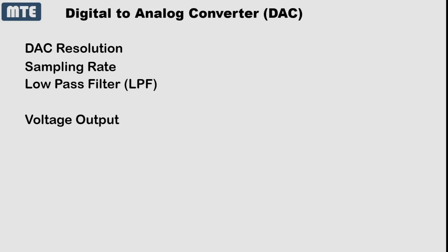Voltage output is used in applications like controlling a voltage-controlled amplifier or providing an input signal to another system. Current output is common in industrial control systems where the signal must travel long distances without degradation. In the real world, many physical quantities are analog in nature, meaning they vary continuously and require sensors to measure them. Let's dive into some common parameters, the sensors used to measure them, and how these measurements are taken.